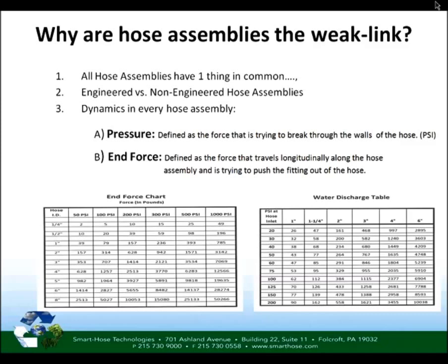For example, let's say we have a 2-inch chemical hose that has a working pressure of 200 psi, and that's printed on the lay line of the hose. An operator comes around and installs 2-inch cam lock and groove fittings at the end of the assembly, which are rated to 125 psi. That full complete hose assembly has now been derated to 125 psi working pressure.